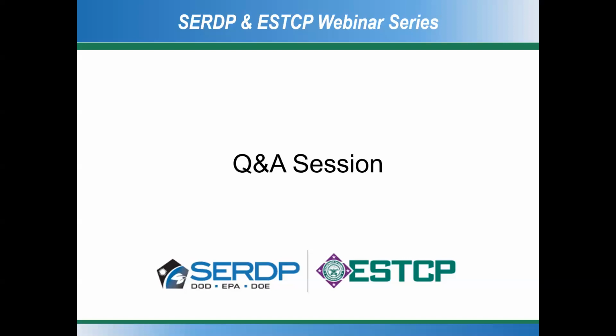The standard requirements out of IEEE 1547 for distributed generation interconnect were used. And then there were a bunch of requirements that the utility put on us, but for the electrical equipment, it was largely industry standard specifications. And then the newer part with the microgrid control was the 2030.7, 2030.8. And then there was a whole bunch of Air Force instructions and Unified Facility Code requirements that we had to meet through the design that were specific to the military. So those are the types of standards that were used.